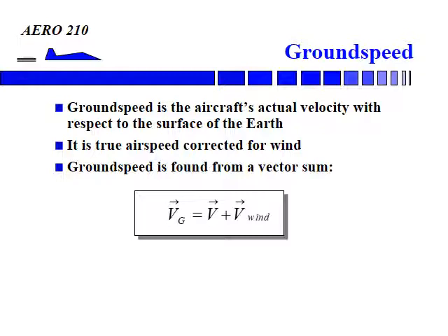It might either help us or hurt us. So in order to determine what our actual ground speed is, we have to make a vector addition of our true airspeed and the wind velocity. And that'll tell us how fast we're going to get where we're going.